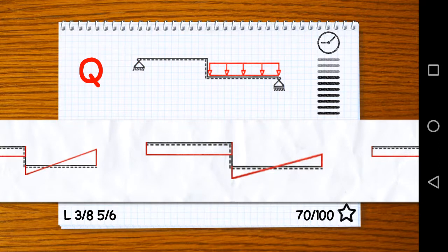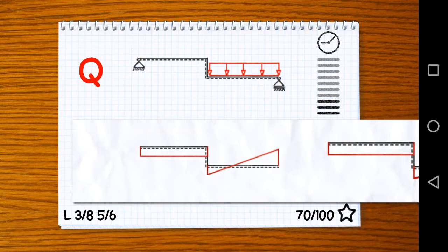The shear forces in the vertical part should be 0. You can find that out by cutting through that vertical part and doing the sum of the forces in the horizontal direction, considering the right side. You see we have a hollow support there. So no shear force in the vertical part. This one could be right, this one could be right. Now which one is the correct one?